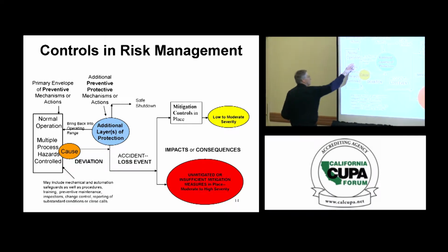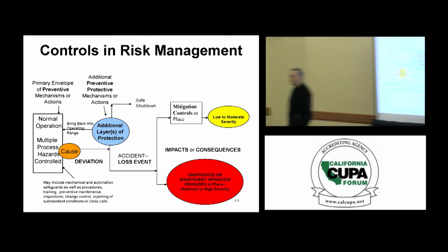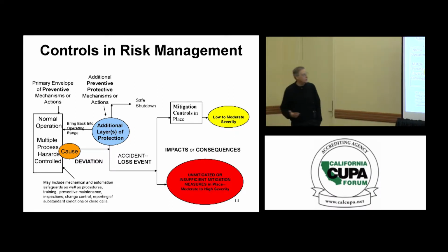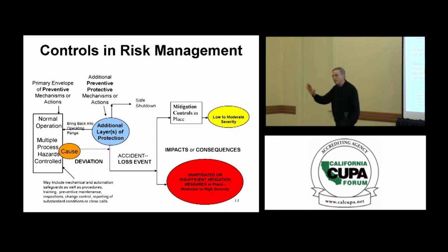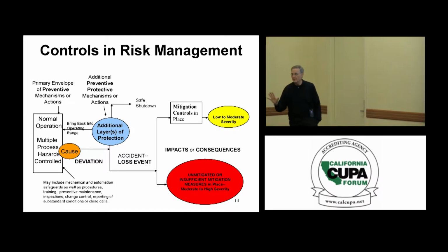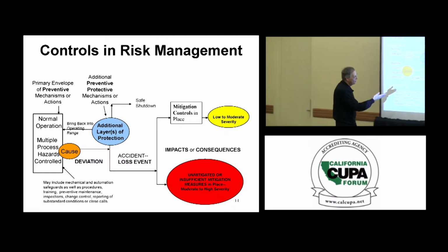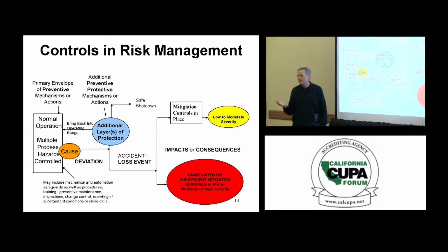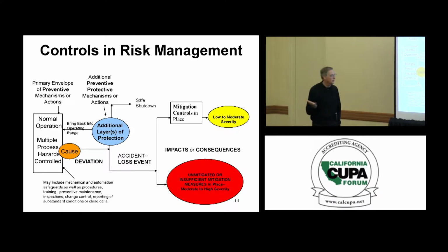So here's what I talked about. Well, here we've got, let's say we've got our chlorine in this storage tank and system. It's contained. It's all controlled. It doesn't mean the hazards have gone away. They're still there, but they're contained. Now, this concept of multiple layers of protection. Let's say we do get a deviation. We have a fire scenario, direct flame impingement on the vessel.